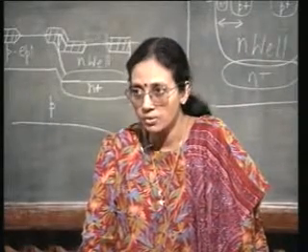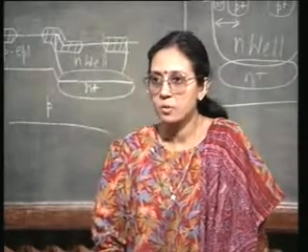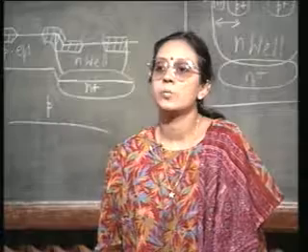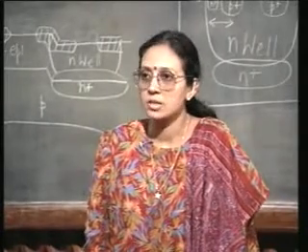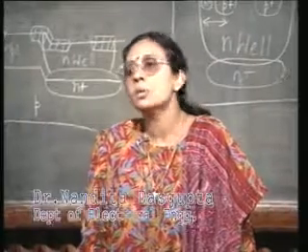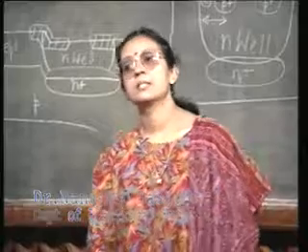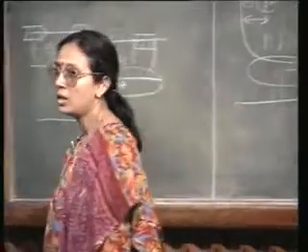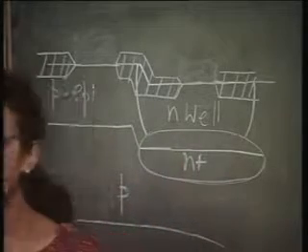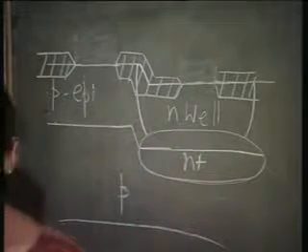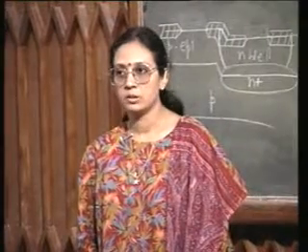It is not the other way around, right. You want to incorporate an NPN bipolar junction transistor in that same CMOS process flow by using a few extra steps. So, this is essentially BiCMOS technology, which is possible because the complex requirements in today's CMOS circuitry have made the concept of BiCMOS feasible.